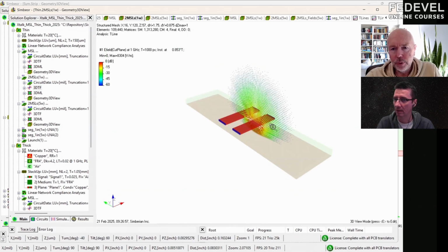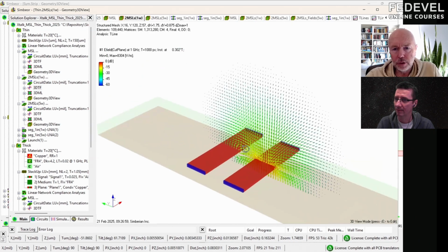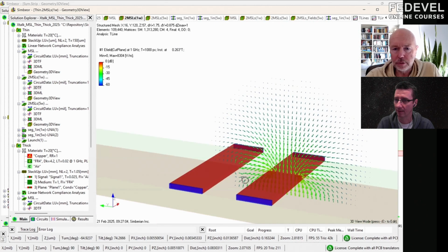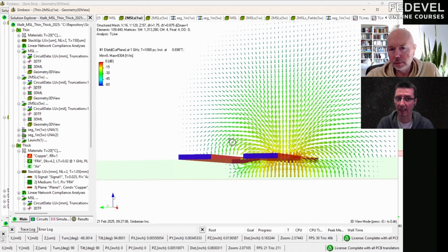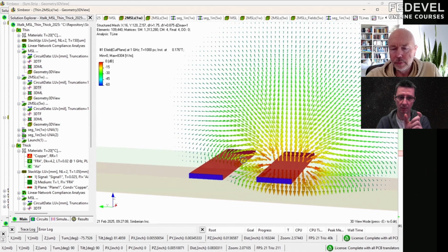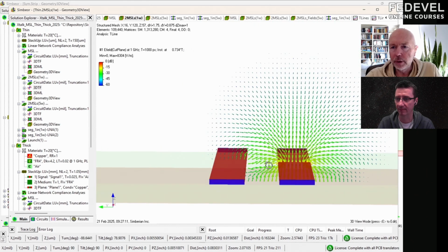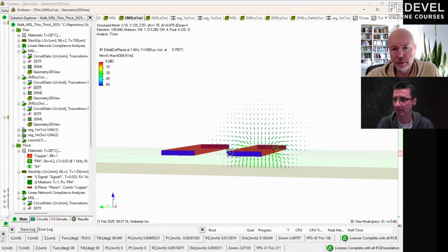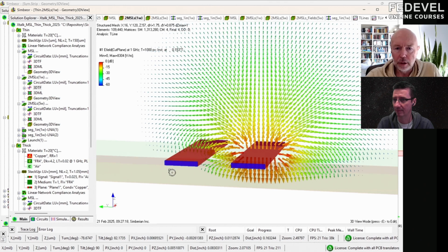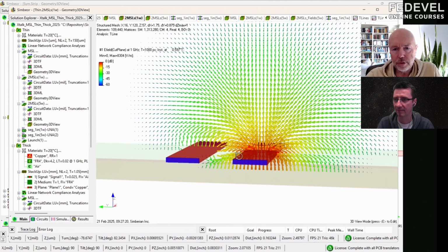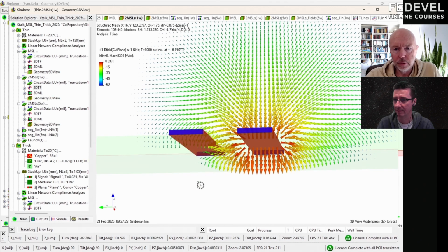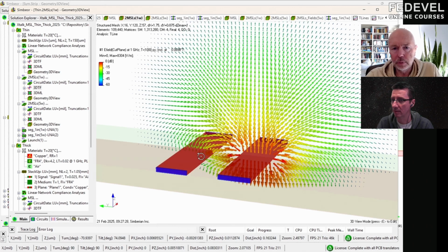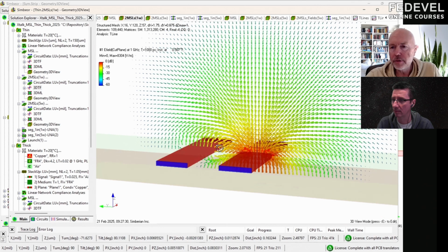Exactly, Robert. That's what we see. We put another track at 1W distance. This is that 1W distance. Naturally, this other track... I would like to stop you. 1W means the width of the track. Width of the track, yeah. Right. And the other track becomes a kind of conductor in the vicinity and gets into the field. And you can see that the fields are getting from up and down to it. And naturally, they create some currents over there.